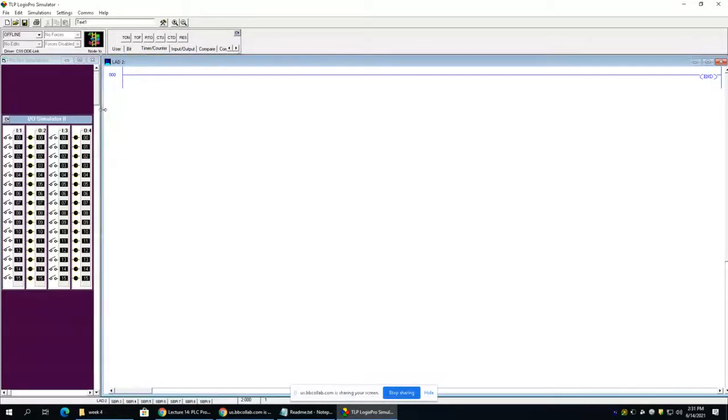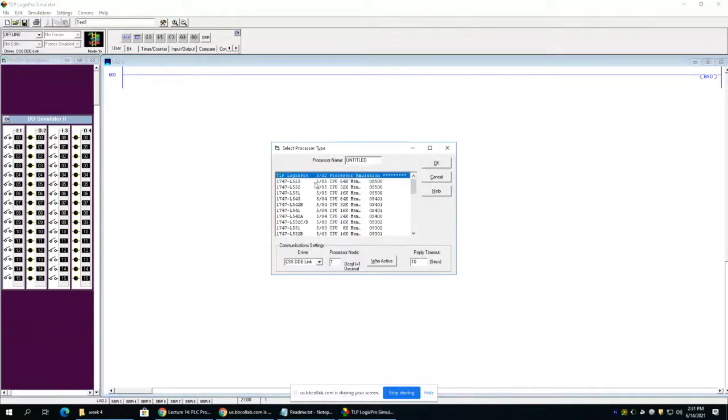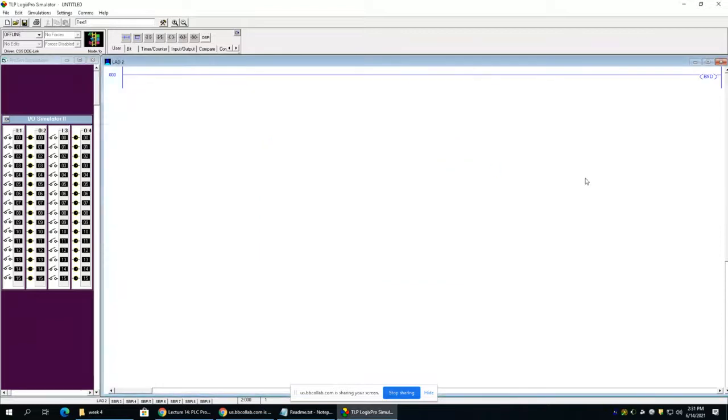So what you want to do here is edit. In your edit window, I'm going to go back to my user instructions, and I want to add a rung. When you start a program, a lot of times if you want to clear out the memory and the data tables, go here to new and just hit that. And then you don't have to worry about any of this stuff. Just say OK, and it'll clear out your program for you. But it erases everything in the data table.